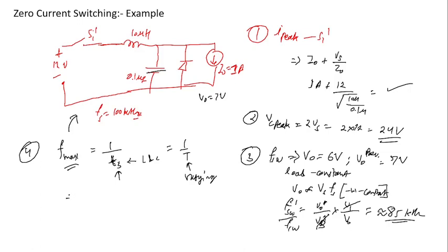So this maximum switching frequency is nothing but equal to 6.8 micro. This is the time period in the case of maximum switching frequency, it would be 6.8 microsecond. Then you just have to inverse it, 1 upon 6.8 microsecond. Then it becomes the maximum switching frequency. The previous question was how we used 10 microhenry and 0.1 microfarad.